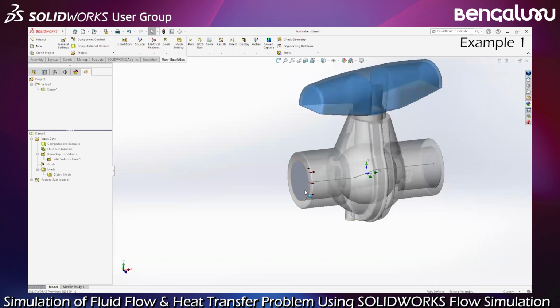If I set flow here or velocity, I cannot set flow here because I have only one inlet, one outlet. Means the flow rate or the velocity at this face will be calculated by the solver. Okay, cannot impose it. Now we may combine flow rate or velocity with pressure as a complement boundary condition.